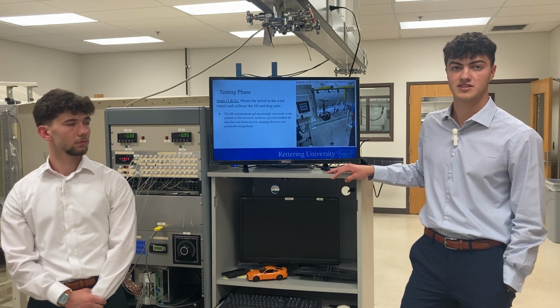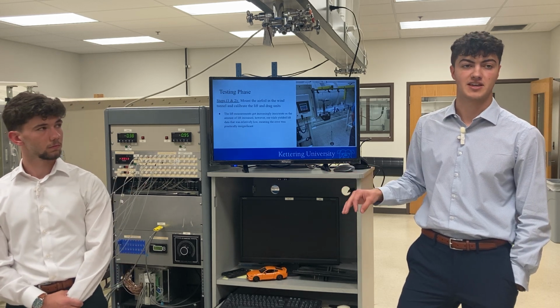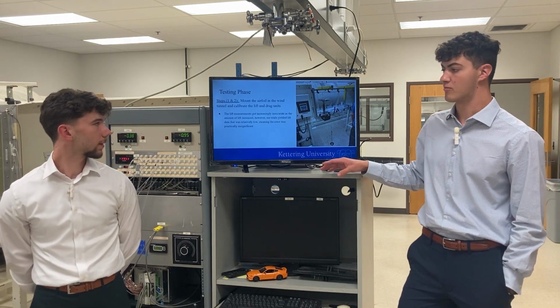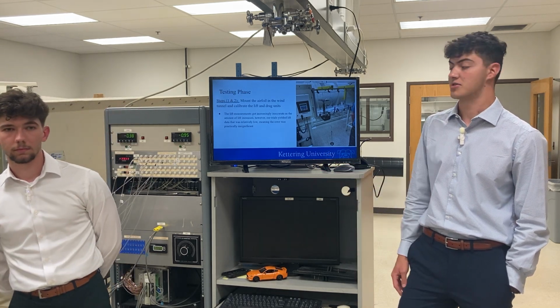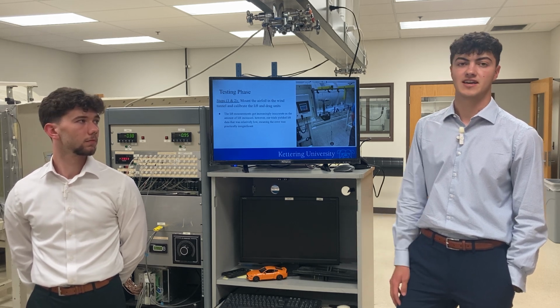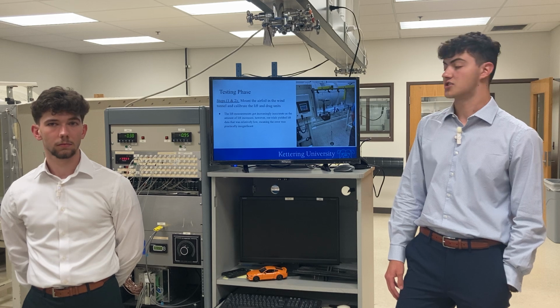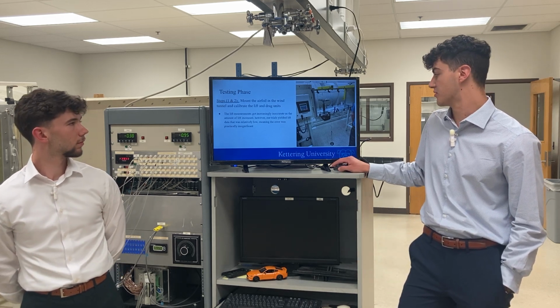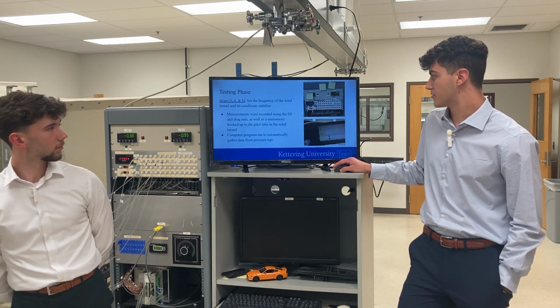So our drag units ended up being very precise, and we didn't have any issues, but we found that with the lift measurements, the more weight we added, the more variance the machine readings gave us. Luckily, the frequencies that we chose to test at were very low, so we basically chose to neglect the variance in our lift measurement due to it being very insignificant.